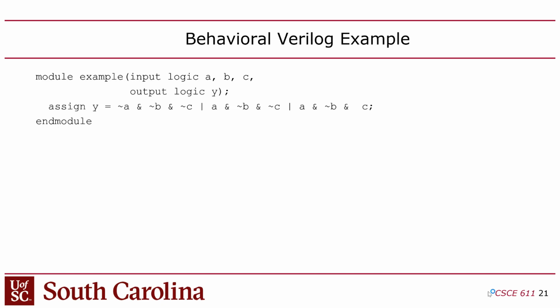And then notice that at the end of the module line there's a semicolon, which is a little weird. That's not like any other language I've seen. And then at the end of the module it says end module, but no semicolon. Don't know why that is. So you have module, end module, no curly braces here. You typically have an end that will define the end, as opposed to a closing curly brace like you would have in C. And then inside the module, there's only one statement, and it's an assign statement.